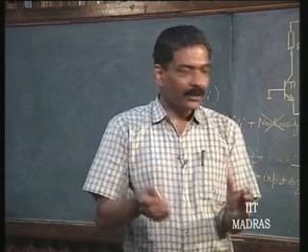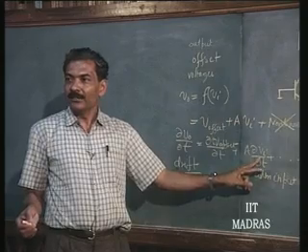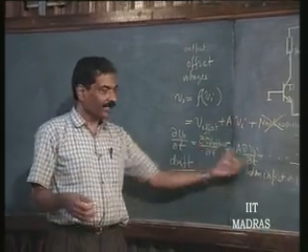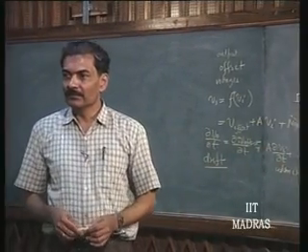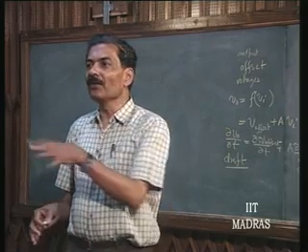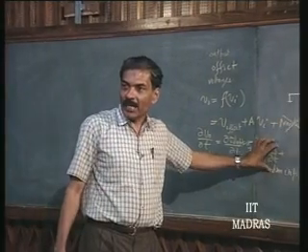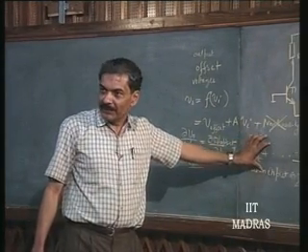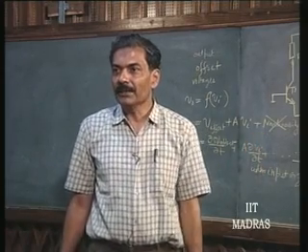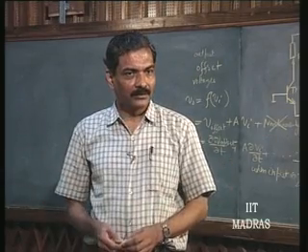And that itself is going to get mixed up, because we cannot make a distinction between this, which is changing with respect to time and which we want to sense, and the drift. That is particularly so if we are not able to isolate this. Drift is a very low frequency phenomenon, and therefore, if our signal itself is a low frequency thing, we are unable to separate this. If the signal is a high frequency signal, then we can separate out the drift component by using a capacitor, just a decoupling capacitor.